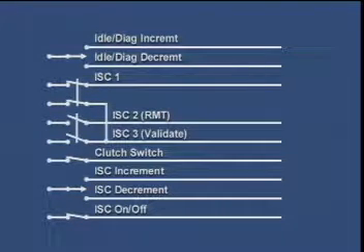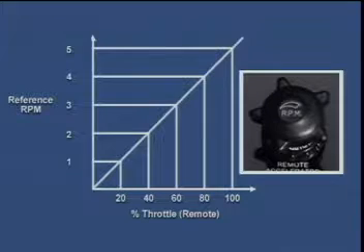One of the switch inputs can be used as a validation input. In this case, intermediate speed control requests are not recognized unless the validation input is on and the ISC switch input has transitioned from off to on. With validation selected, 2 switch-activated ISC speeds are available. To switch to any of the other settings, the switch is moved to the position corresponding to the desired speed.